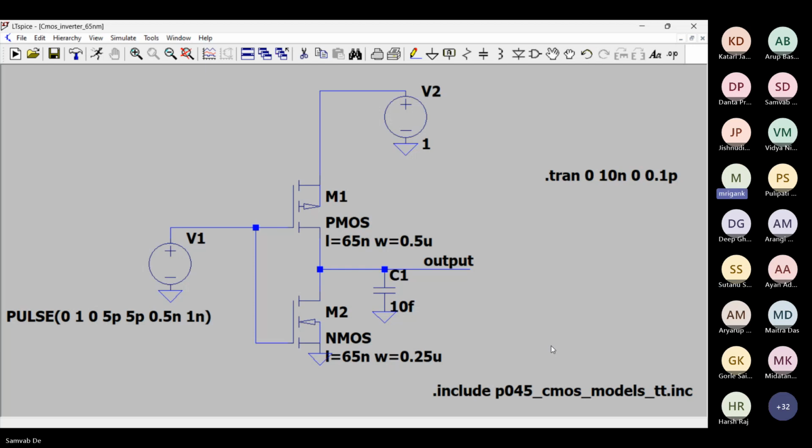Yes, because the capacitor is taking more time to charge, so definitely the current will also remain for longer time. So some power consumption will be there. More power will be consumed. Power consumption will definitely, what is the power consumption dependent upon? We have discussed yesterday. For CMOS, I think we did not derive the power consumption. I will do that. So here, that is a good point, but I'm talking about transient waveform. The power consumption will increase.